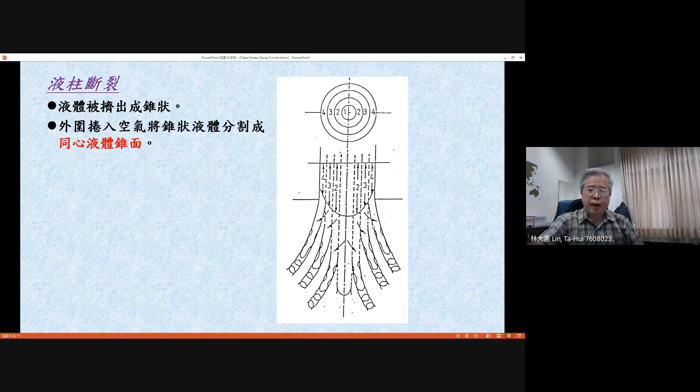Okay, these two effects will make the spray into a concentric conical spray. Concentric, there are several cones, right? There's the outer cone, and then the center cone around here, and this cone is produced by region 2, and this cone is produced by region 3. Okay, and with this kind of structure, you may have air entrainment into the interior region between the different spray cones.